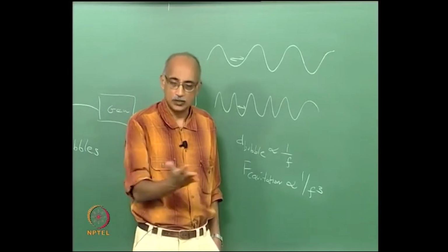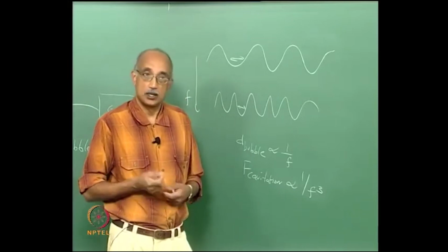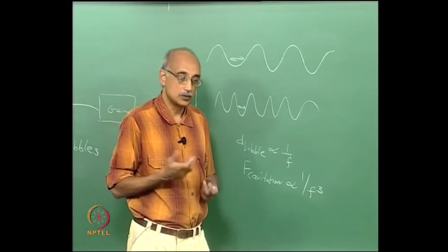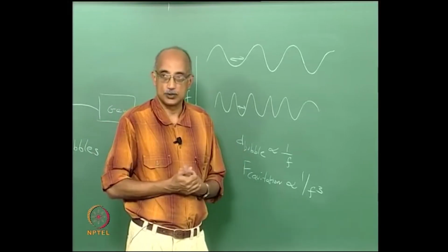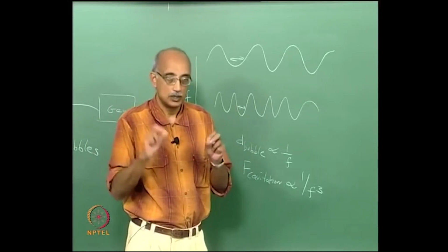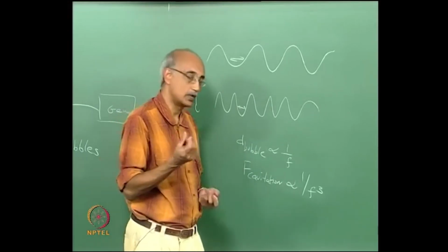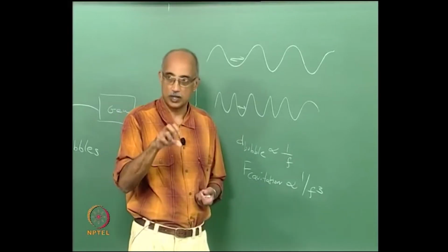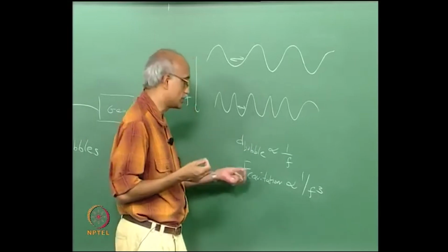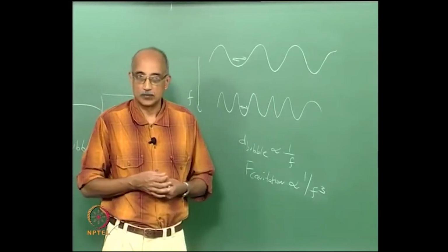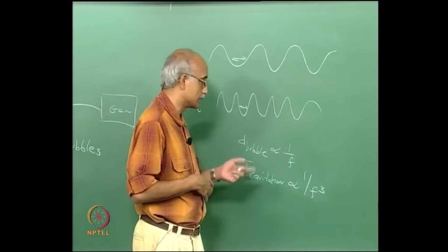which is good and bad. It is bad when you are trying to clean surfaces and materials, because it can actually cause damage to the surface. It is good when you are trying to, for example, fragment a material deliberately. For example, if you have agglomerates in solution and you want to break them down into individual particles, cavitation erosion is a way to do that. Or if you want to take larger particles and break them down into smaller sizes, for example micron to nano, then this cavitation erosion actually helps you do that. It is a process called sonofragmentation, which we do a lot of work on in our lab.